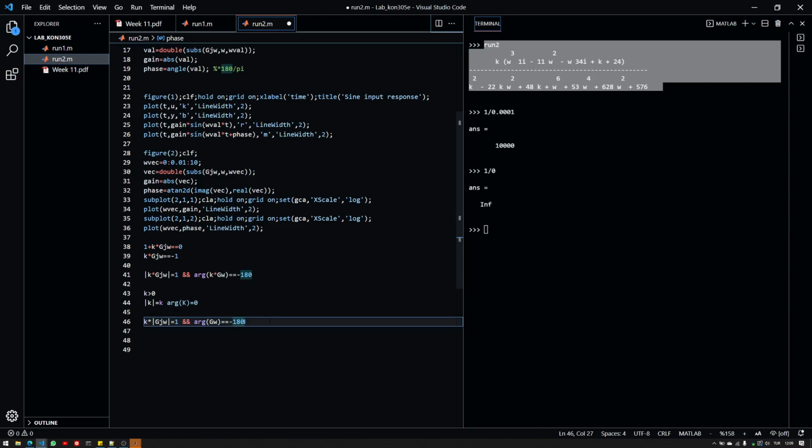Now, this line 46 can help me out in determining what the p-type controller should not be, or at which point k causes instability. Since this equation here is only based on j omega and the argument of j omega, this means that our scalar p-type controller cannot contribute phase angle because it's 0. But it can only contribute a gain, which makes sense because it's a p-type controller, a static gain.